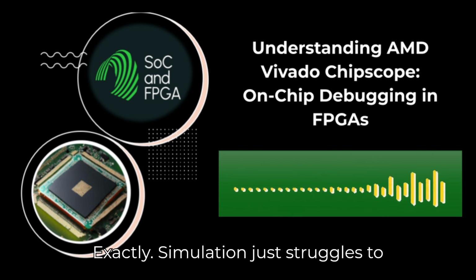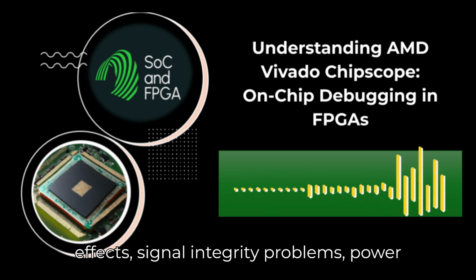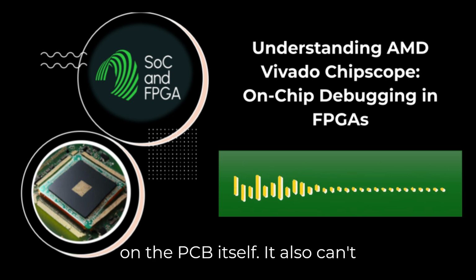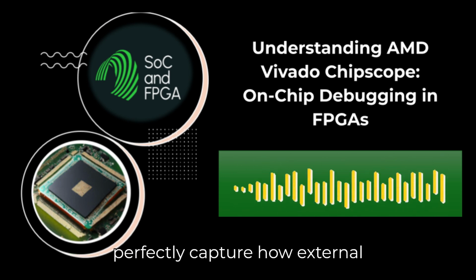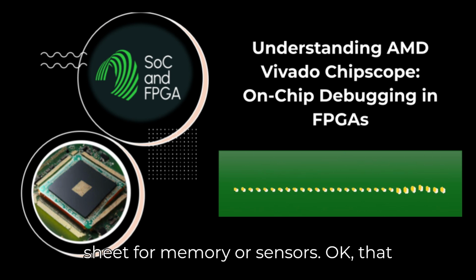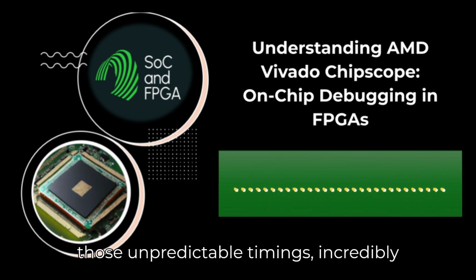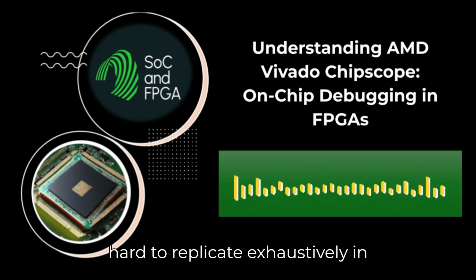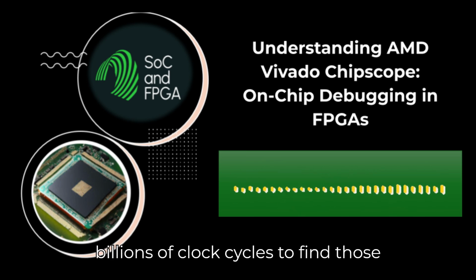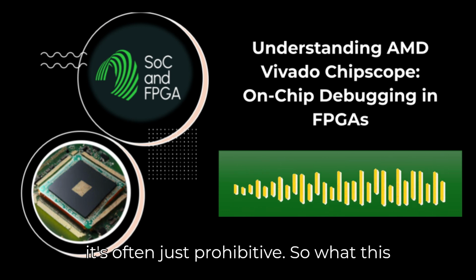Right, the stuff you can't predict. Exactly. Simulation just struggles to model things like board-level effects, signal integrity problems, power supply noise, subtle impedance mismatches on the PCB itself. It also can't perfectly capture how external peripherals really behave. Maybe the timing deviates slightly from the datasheet for memory or sensors. And asynchronous events, those unpredictable timings, are incredibly hard to replicate exhaustively in simulation. And forget trying to simulate billions of clock cycles to find those really rare performance bottlenecks or intermittent glitches. Computationally, it's often just prohibitive.